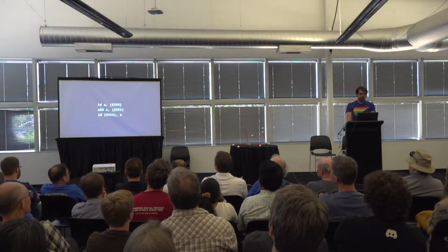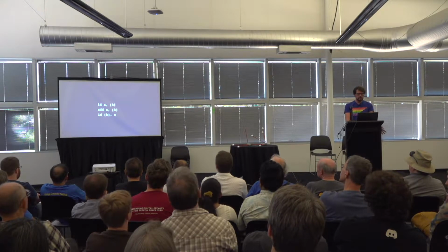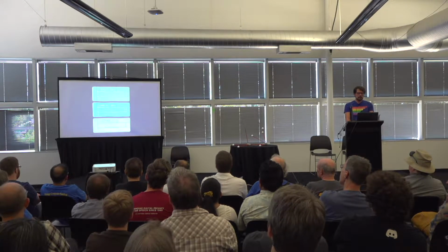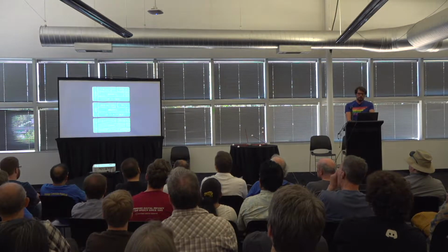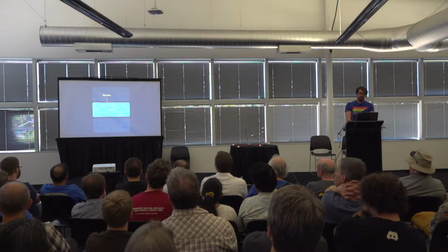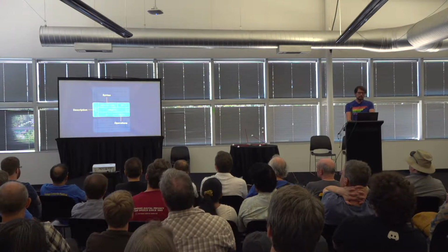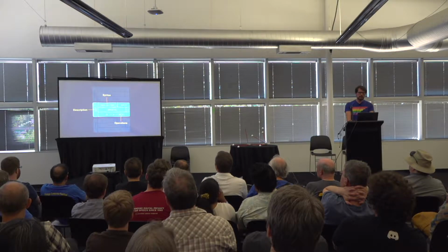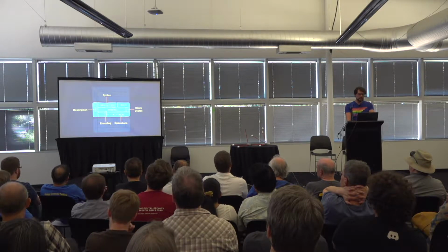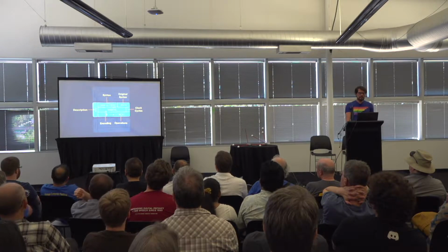The generalized versions of these instructions we just saw use K as a placeholder for a memory address as an argument. These cards are a quick reference for the instructions. This is the generic syntax of the instruction, a short description, the exact operations in pseudocode. This one takes memory address K and adds it to A, the accumulator, the encoding of the instruction in memory, and the number of clock cycles. What do I mean with original syntax?